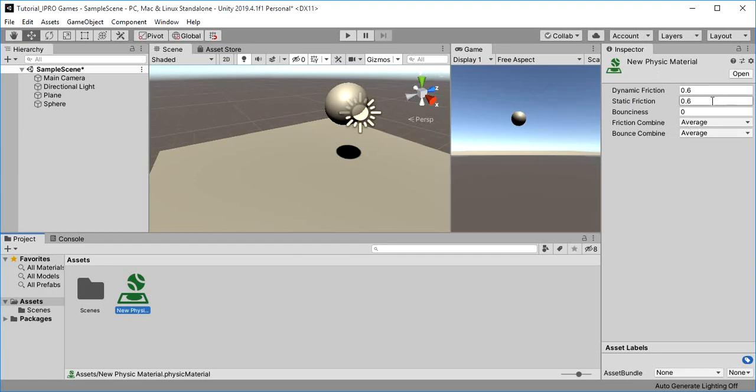You'll see dynamic friction, static friction, and bounciness. I think both of the frictions represent friction. Dynamic is for when the object is moving, how much friction you want. If it's infinity, it won't be able to move. Then we have the bounciness. The range for dynamic friction is from 0 to infinity, then 0 to infinity for static friction, and for bounce 0 to 1. I'll set 0 for the friction right now because I want to do something experimental.